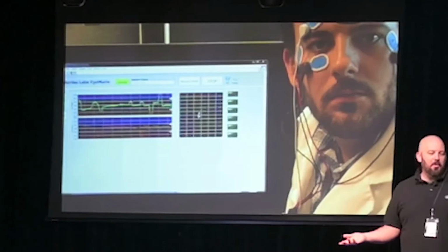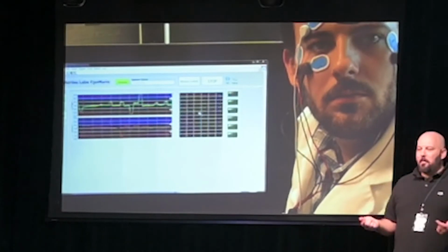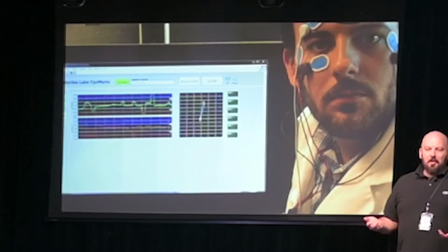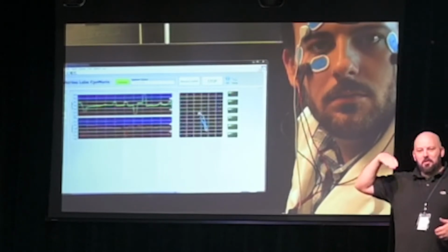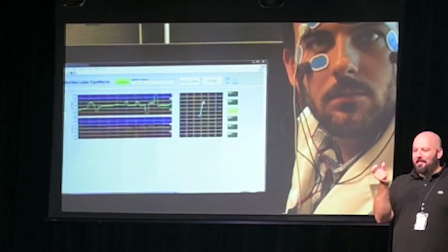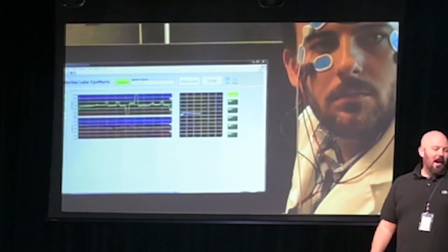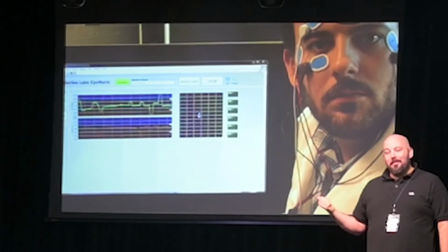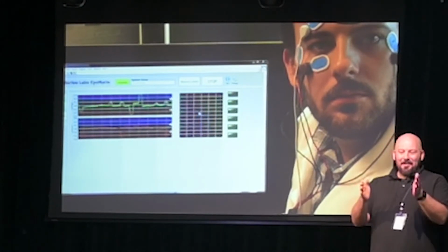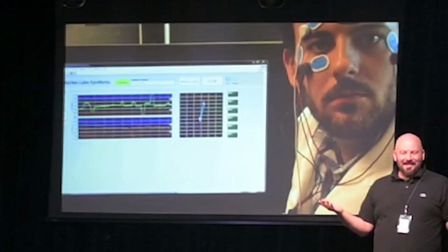So here's an example of where I showed some motion. This is from one of the old Waterloo Labs videos, where I've rigged up an electrooculogram that uses these silver chloride electrodes on your face that can measure the dipole potential. Your eye is basically polarized. The problem was, when I was testing this, I had to look away from the screen to test it, and I'd look back and I'd miss it.